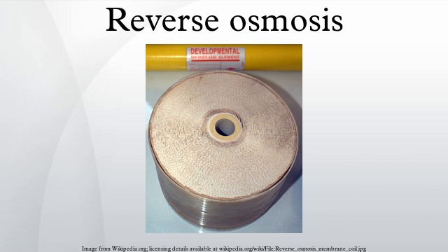The process of reverse osmosis can be used for the production of deionized water. Reverse osmosis process for water purification does not require thermal energy. Flow through reverse osmosis systems can be regulated by high-pressure pumps. The recovery of purified water depends upon various factors, including membrane sizes, membrane pore size, temperature, operating pressure, and membrane surface area. In 2002, Singapore announced that a process named NEWater would be a significant part of its future water plans.